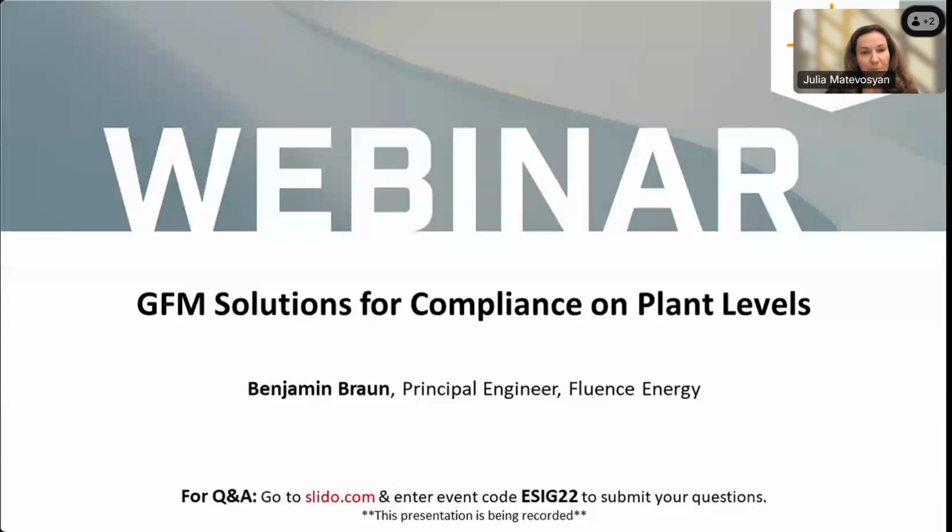Just to introduce the webinar today, you have probably seen recent updates to grid codes enabling grid forming operations, and they open up opportunities for a multitude of applications. This in turn has exposed a gap between component level controls and complete grid code compliant plant level solutions. This presentation will highlight additional requirements and considerations to convert a collection of subcomponents into plant level solutions that are compliant with the latest grid code requirements for grid forming operations.